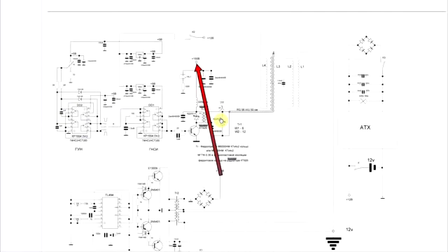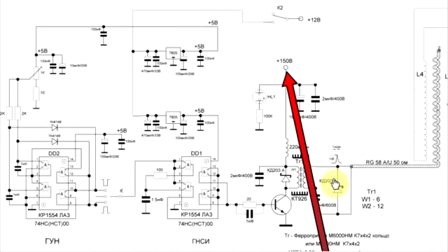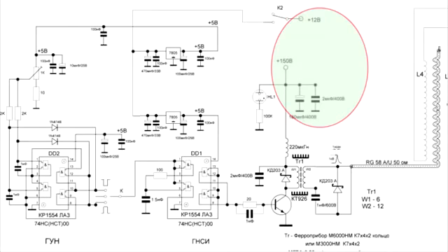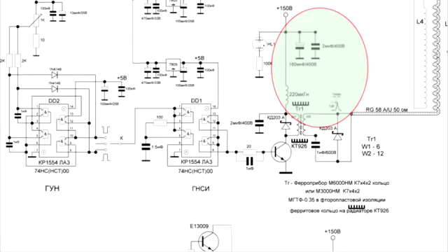That 150 volts will be passed to the 150 volts terminal of the upper impulse forming circuitry. After 150 volts is passed to this terminal, these two capacitors serve as a part of the pi filter, smoothing the pulsating DC from the rectifier. The neon bulb gives an indication of the presence of 150 volts at that terminal. The 220 microhenry choke prevents any AC component from going back to the DC 150 volt line.